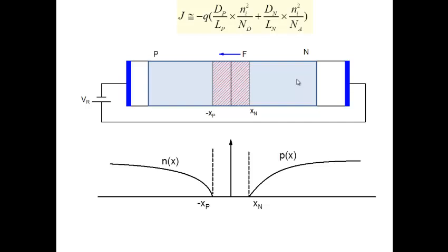If you create a hole here, the hole has a chance of coming here before recombining. But if you create a hole somewhere further away, the hole has less of a chance to enter the depletion region here. Okay, so anyway, let's see how the carriers flow here. We are looking at this particular region, this part. And what happens is you create carriers. Generation is all the time taking place. So you create an electron and a hole. Now, there is a diffusion process because there's a gradient, so the hole starts from here and moves here.